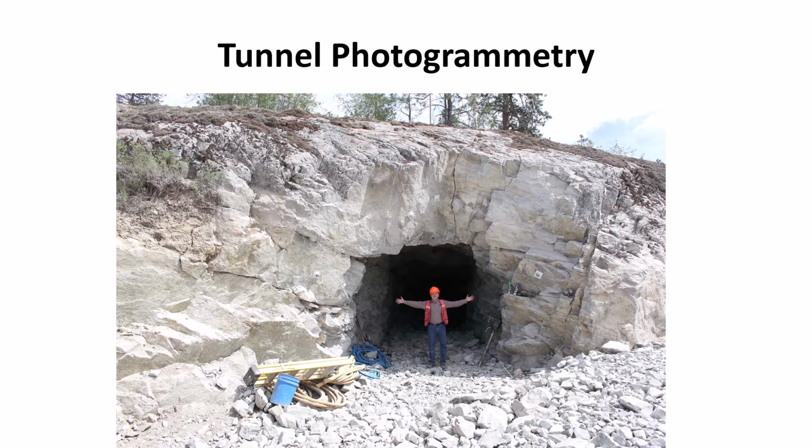And once you do all that, you're ready to do some field work and start to acquire some images. So here's a tunnel. That's me standing there. I used photogrammetry to survey that tunnel as it was being excavated. So think about what we've talked about, and think about how you would set up your camera stations, where you would set them up, how you would adjust the camera settings to be able to survey both the portal area, and then as you go into the tunnel, how would you set up your camera to acquire those images?